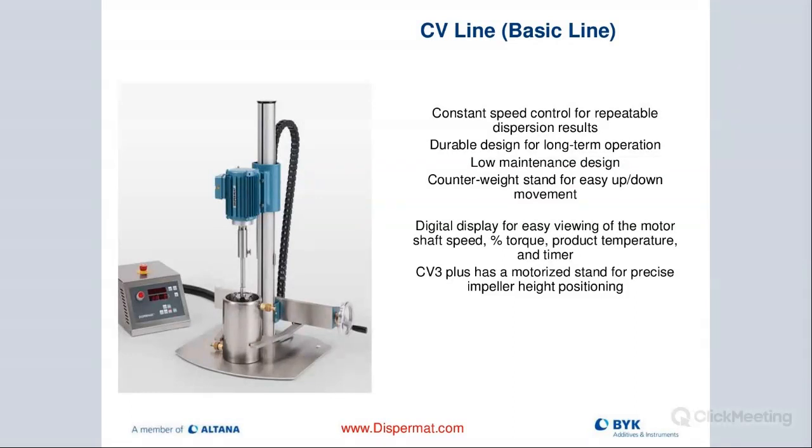It also comes with safety features. So we have the container clamping system, that wheel right there ensures that the container is tightened and always centered perfectly underneath the dissolver blade. There is a sensor back here that measures the pressure, and if the pressure sensor does not read that it's tightened enough, the machine will show you on the display and it will not run.